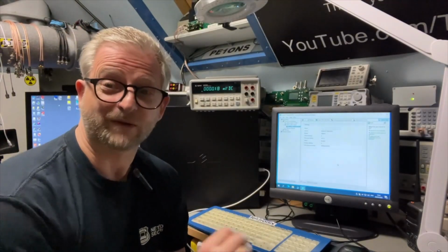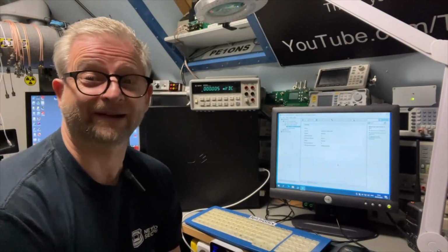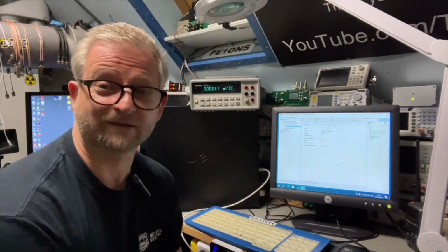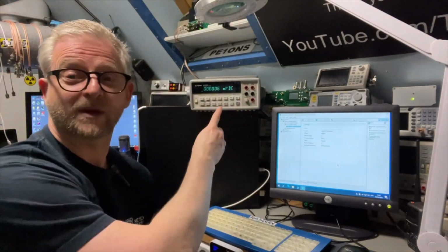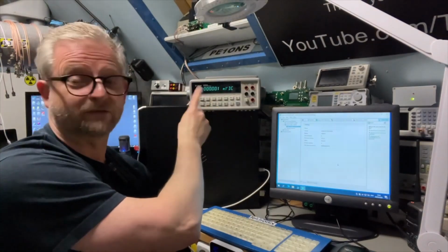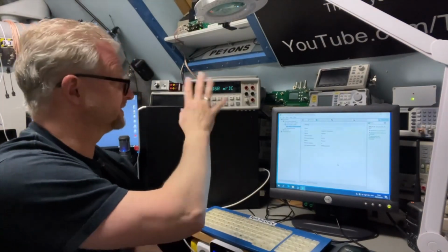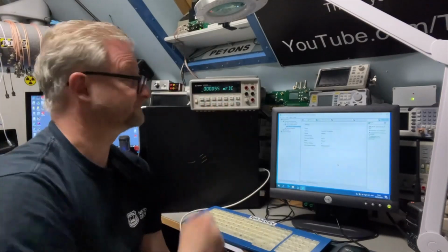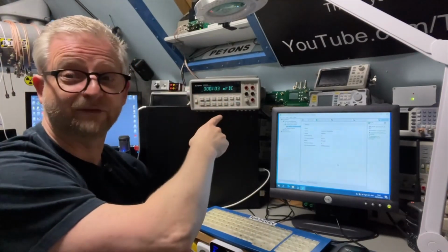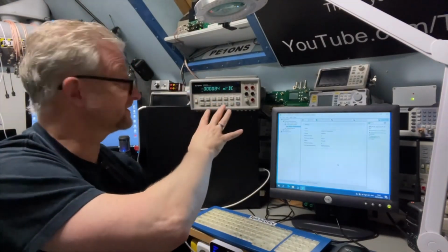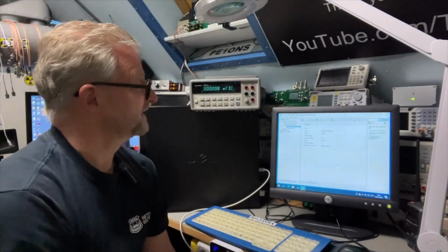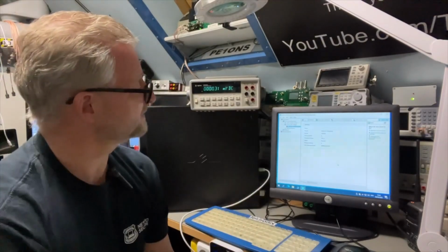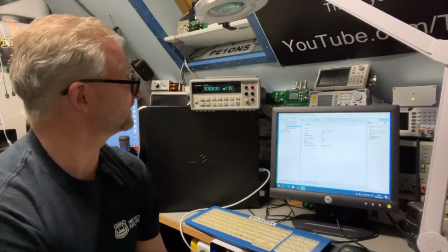So if you have a card with PCI, just use it on Windows 10 and you can just install and it just works. Just remember to switch the device over from serial to GPIB if you have that option. If you manage to get through this menu, which I think still is terrible, but the meter is amazing. And well, we were able to communicate with the device, so that's nice.